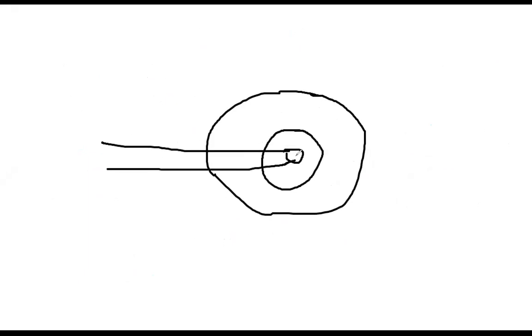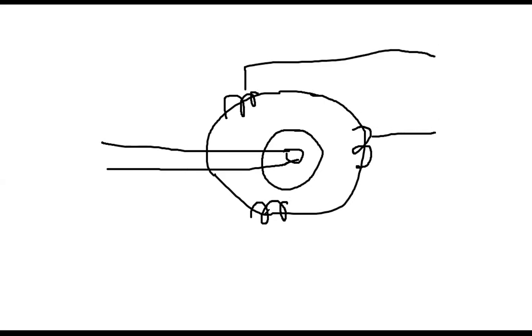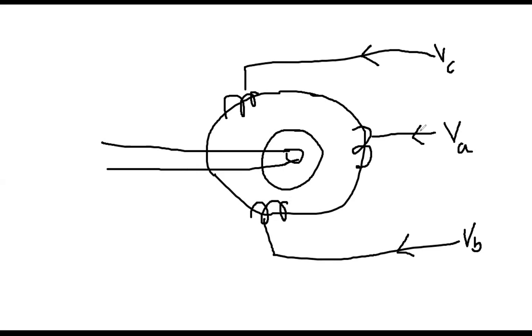Okay, so let's start. We are discussing the three-phase induction motor. Everybody see, this is one body, and then this is another body to which the shaft is connected. And this will rotate later. So on this body, three-phase coils are placed 120 degrees apart. Because we are discussing the motor, on the stator body we will apply three-phase voltage. So see the direction. I am applying the three-phase voltage, for example VA, VB, and VC. Consequently, the currents are flowing, IA, IB, and here IC.